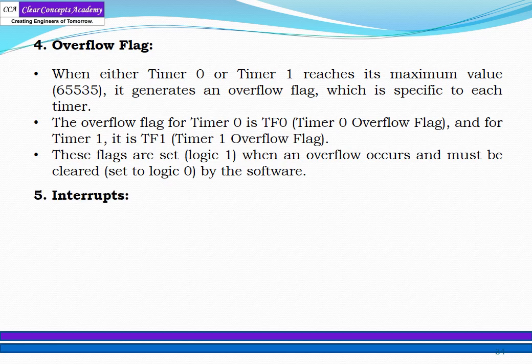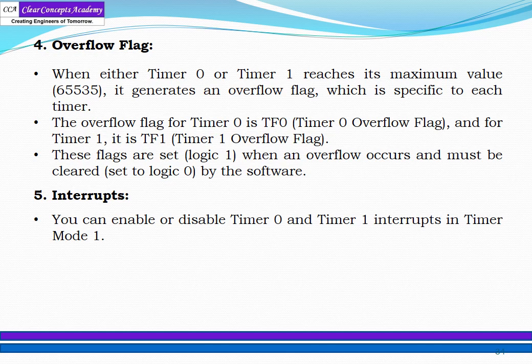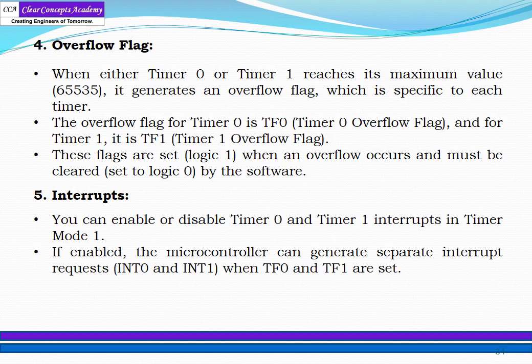Now, interrupts. What is an interrupt? You can enable or disable timer 0 and timer 1 interrupts in timer mode 1. And how will this be enabled? That will be enabled in our IE register, the interrupt enable register. If you do a proper setting in the IE register, then this timer interrupt will be enabled.